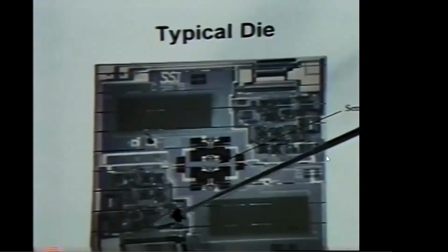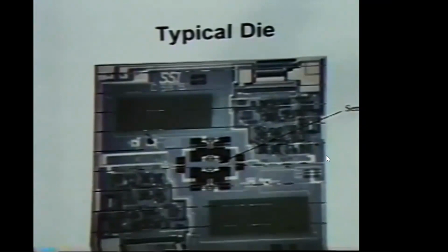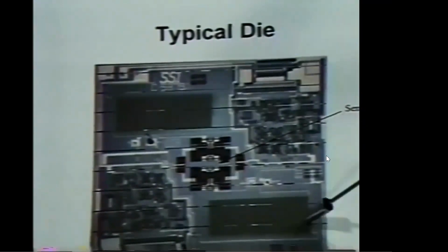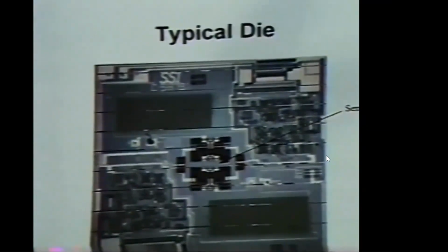You find also an op amp, which in this case is the buffer amplifier, as well as some very large resistors that we use for trimming the offset. These are, by and large, bigger than they need to be, so that we can easily reduce the size of the die. In fact, that is currently in process for the next generation pressure sensor.